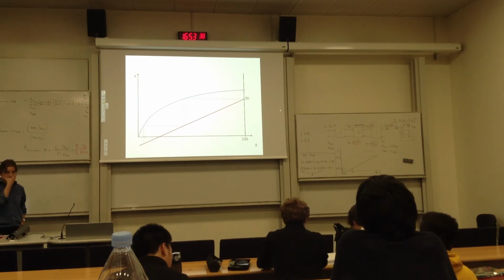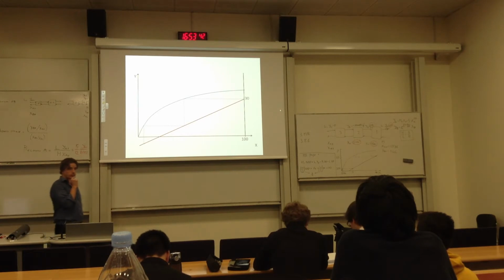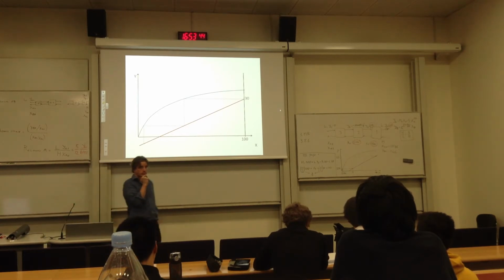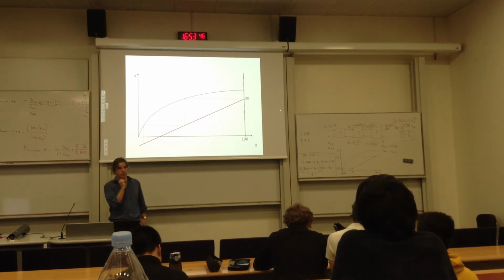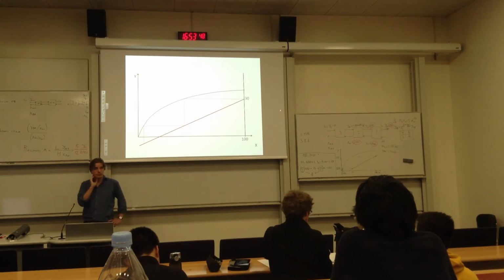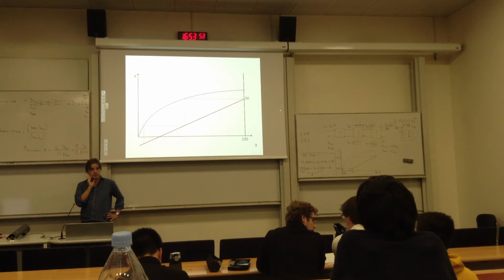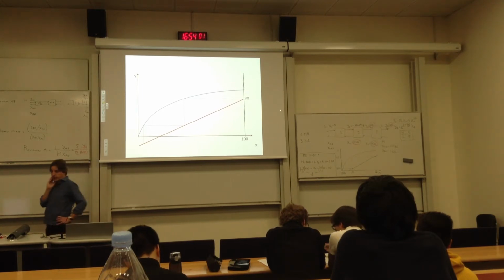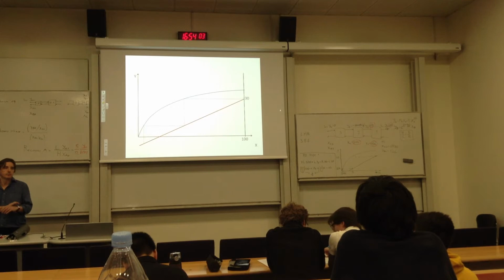And then you can calculate, using this graphical method, what is y0, and you get something like 3 or something. You then use this value to calculate what the operating line should be to move it. You move up again, and you have a discrepancy at x0, and you just do this 3 times, and things fit together.